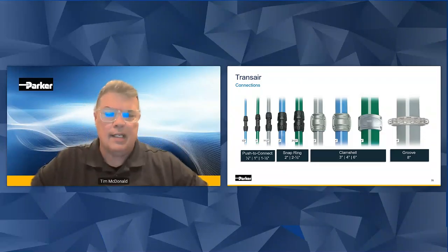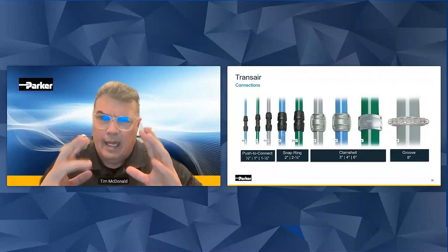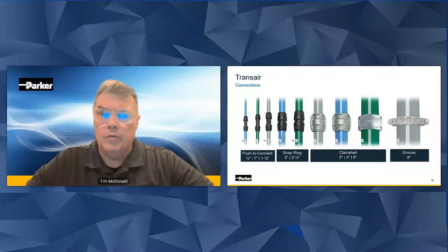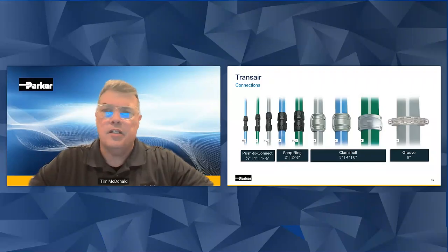With your push to connect connection, it's just that very thing. It's like a shark bite fitting. You take the fitting out of the box, you push it on the end of the pipe. You've got 16 stainless steel teeth that hold that into place. It is 100% reusable. It's one of the quickest installation technologies in the market today.